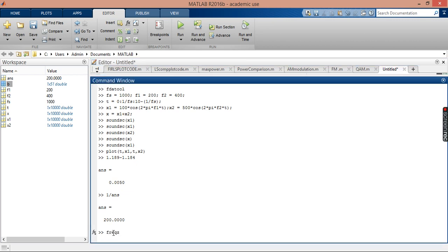By the way, if you're interested in looking at the frequency response of the signal, you can use the freqz command, the frequency response through Z transforms. If you evaluate the Z transform on the unit circle, because the Z transform is a generalization of the discrete time Fourier transform, and if the Fourier transform exists, the region of convergence must include the unit circle. So in Matlab you can use freqz, the built-in command. Let's have a look at X, and evaluate this at, say, 512 points, or 1024, depending on the resolution you wish to use.